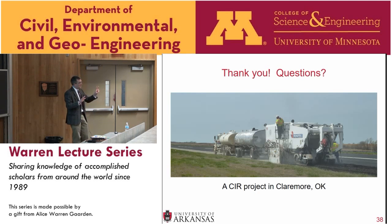And we tried to do two things. We tried to mimic approximately the same amount of material that was coated with material that was open. Because then when you actually start mixing the asphalt emulsion in during the mix design process, some of that asphalt emulsion is coating an existing coated surface, but some is coating a fresh surface. And those are two very different mechanisms. Did that make sense? Yeah. Okay. And what was the second question?